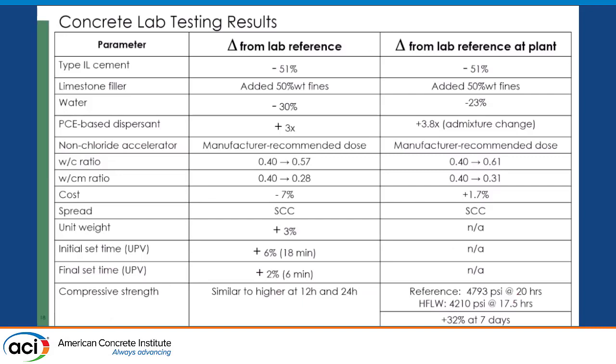So in the end, that was our initial mix in the lab, right, without the producer here. This is after the lab at the plant, so we kept the same. We actually had to adjust the water a little higher. They wanted to test a different chemical mixture, a little less efficient but not as much air entrainer. So it was actually a better admixture, but called for a little bit more. So let me see what else. The cost of that mix that you saw is 1.7% more than the reference.